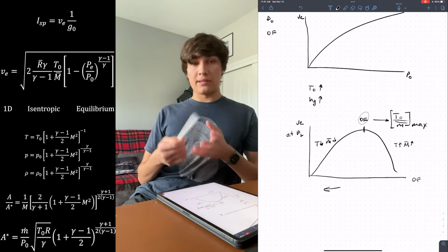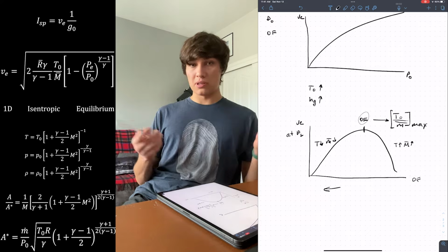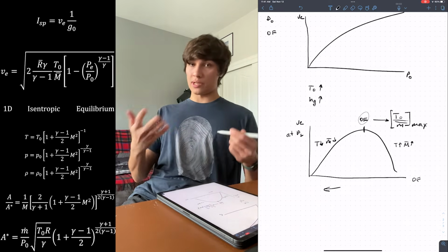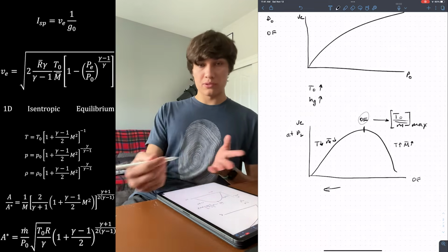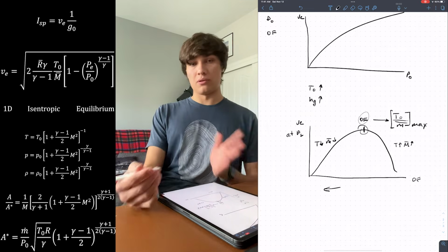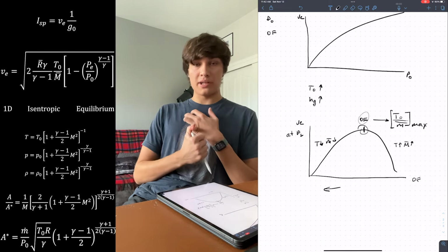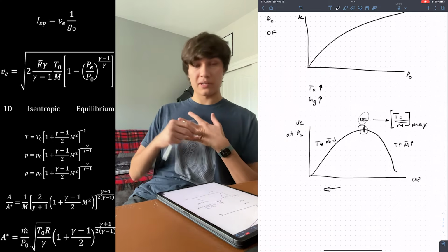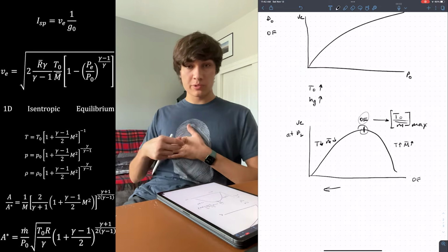The practical way to find the ideal oxidizer-to-fuel ratio is to do a parametric study in a combustion solver like CEA, where you specify some fixed pressure that you have chosen, which is your design parameter, and then you vary through a range of oxidizer-to-fuels, and then you'll see a plot like this, and then you'll choose your ideal oxidizer-to-fuel ratio for your rocket. The same way that running a higher pressure engine is better for efficiency but harder to build through an increase in temperature, an increase in convective coefficient, and an increase in hoop stress.